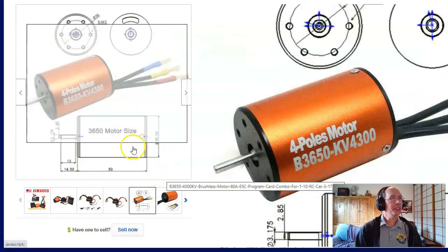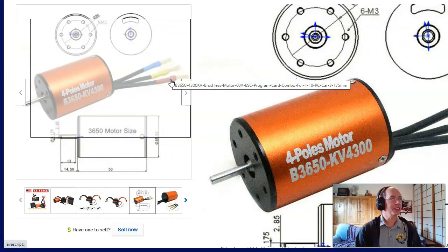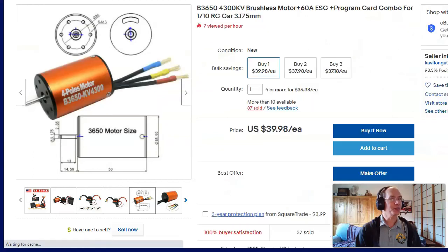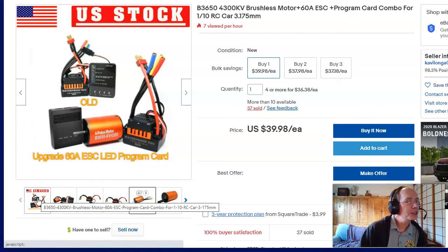But you need 3 phases. It's got 3 wires. If I give this a DC signal, it's going to stare at you, confused, not knowing what to do. I need a 3-phase motor driver to go with it. This one, of course, comes with the motor driver. I feed it the voltage, 0 volts, 36 volts, whatever this one takes.